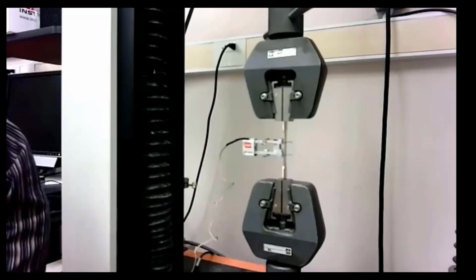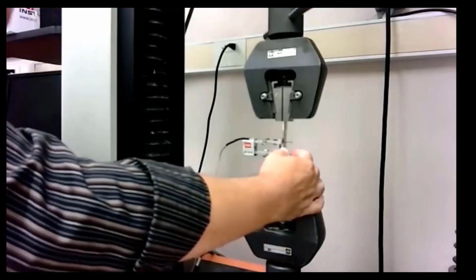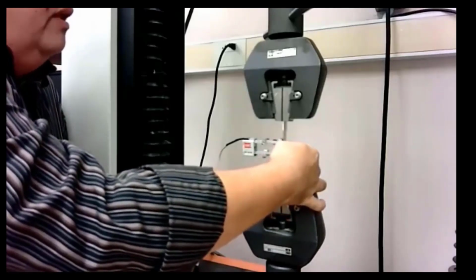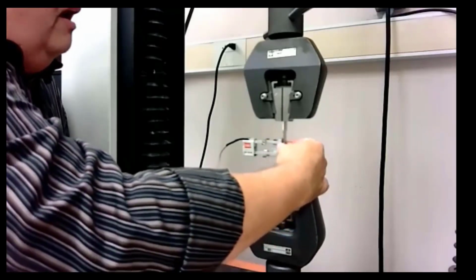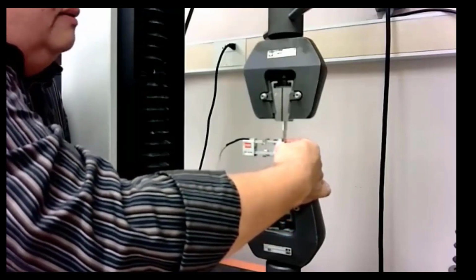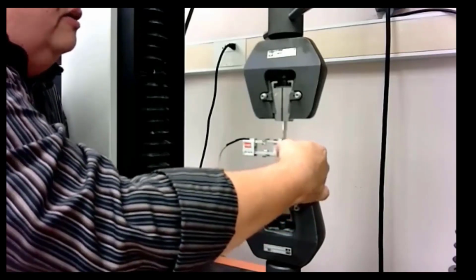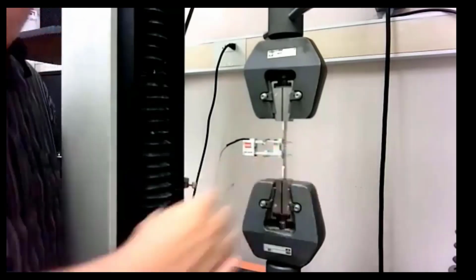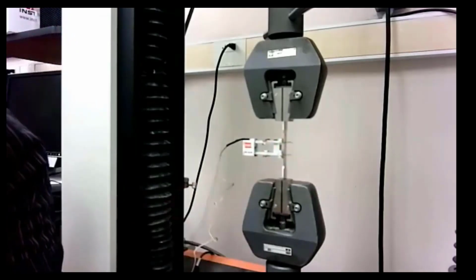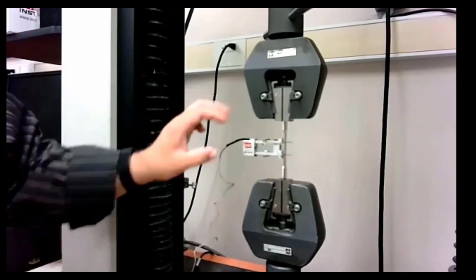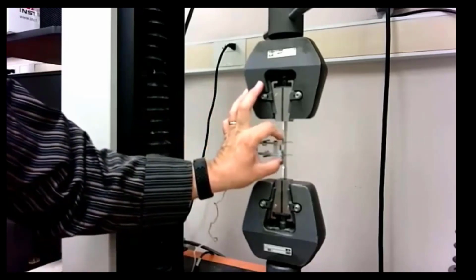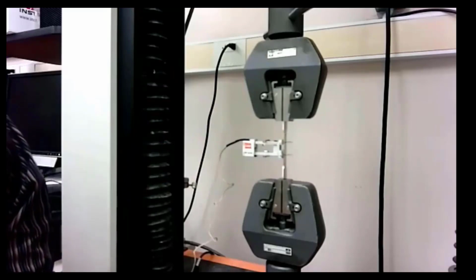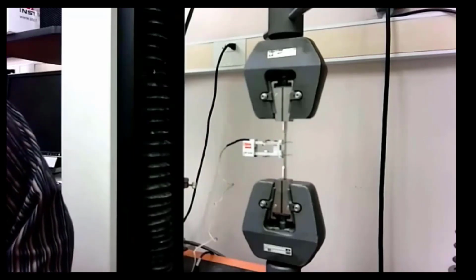To check and adjust the other two, I simply pinch the specimen from the opposite side as the extensometer. And since it's very close to the same width, I can feel whether or not it is centered top to bottom, or front to back. And if both the top and the bottom are centered, then that implies that it is vertical as well. Finally, I squeeze the jaw all the way together to make sure that it is at 0. Now that we have it installed, we're ready to start our test.